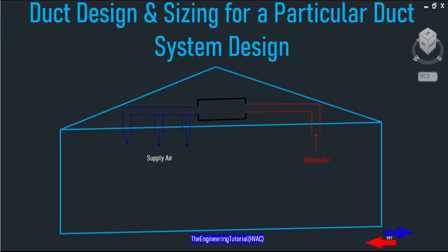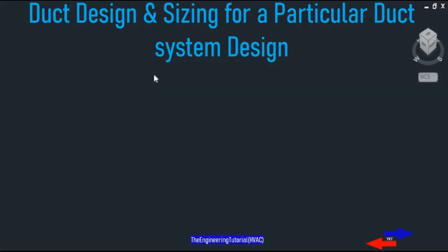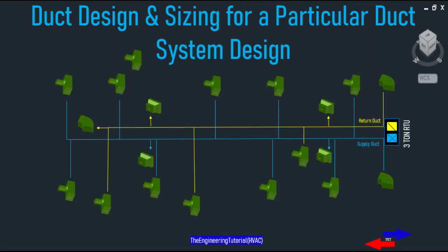When designing a duct system, the air handler should be installed in a central location of the building that allows you to minimize the length of the longest supply and return duct and keep duct runs as short as possible, and position duct to avoid obstacles and minimize the number of fittings required.